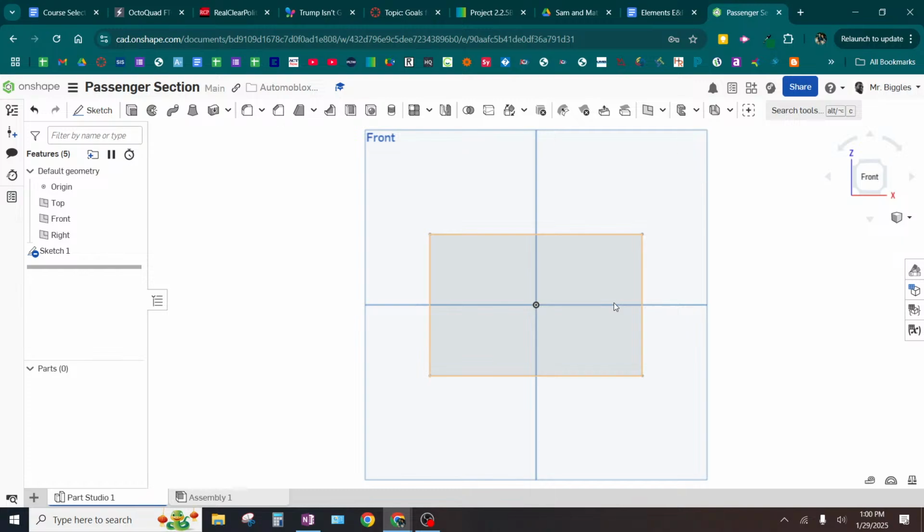So what I'm going to do is measure the width. Now, my recommendation: do you see what I'm doing here? I'm exaggerating this. If you see I'm at an angle, you want to avoid that. How do you make sure that you're perfectly straight and not at an angle? One thing you can do is measure near an edge, so I can make sure my calipers are flush with a surface. Notice I have it around the shape, but flush with the top or the bottom of the thing I'm measuring. That's a little trick to help ensure it's straight.